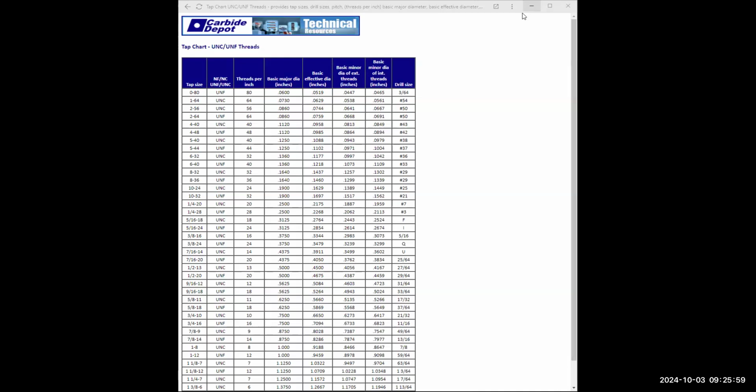And I'm going to type in CSK, which stands for countersink, space, percent C, space, 0.75, space, times 82. Now, percent D gives you the degree. And then click on your screen. All right.